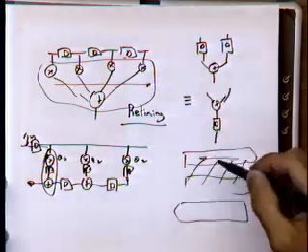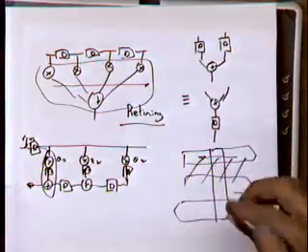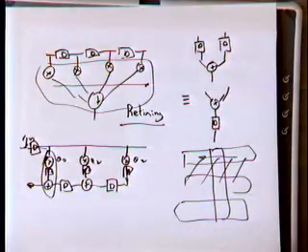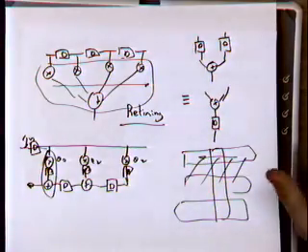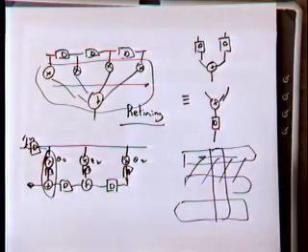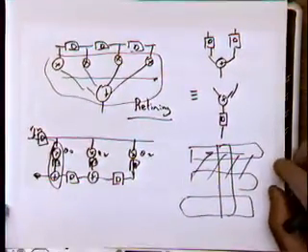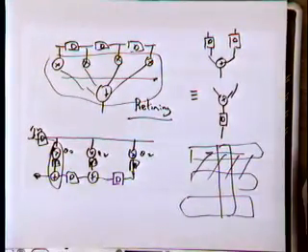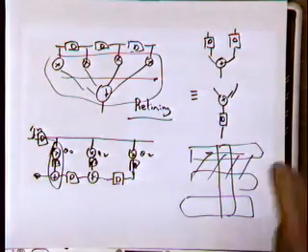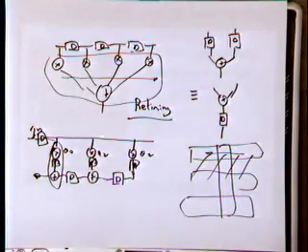There was one group that also considered the adders and said, well, let's do the same trick as a Wallace tree multiplier. Every adder is 3 inputs, 2 outputs. Can I restructure this whole thing to play around with that and basically have reduction? And that came out quite nicely as well. So a lot of really cool ideas, I think. And as I said, I saw you use every trick in the book that was out there.